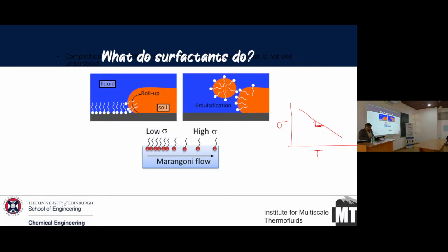Okay. In some cases, for example if you have a water-butanol system, which is a mixture, your surface tension and temperature profiles are slightly different. It's actually a parabolic profile. So there is a region of minimum surface tension, and then it tends to climb back. So these are called self-rewetting fluids. These are not fully surfactants, but they are surfactant-like fluids. But they are not surfactants chemically. They don't have these two different tails.